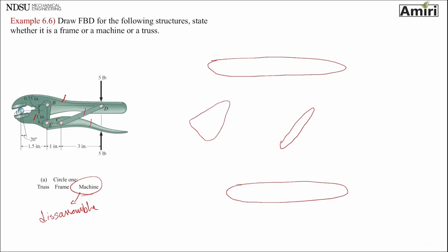I usually like to start with the easiest one, which is a two force member. And I like to draw that one in tension or compression, it really doesn't matter. Let's put it in compression. Okay, so that one is going to be FCD. Now that I've drawn this one in compression, for the other members, I have to draw them in the opposite direction.